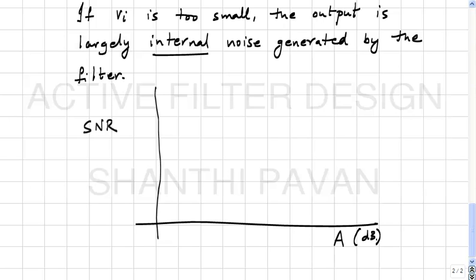You can never plot an absolute quantity in dB. dB is always a logarithm of something. You can't take the log of a number with dimensions. It must be normalized to something. I have chosen that normalization to be 1 volt, so that A in dB simply means 20 log A by 1 volt.